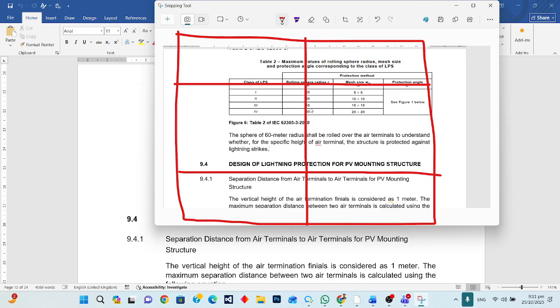Some areas, where we can't do excavation for different reasons, like mines areas, the client will not accept excavation of the solar sites. So the process is that we have to do everything over the ground, like the earthing and the foundations, everything should be in the overground area.